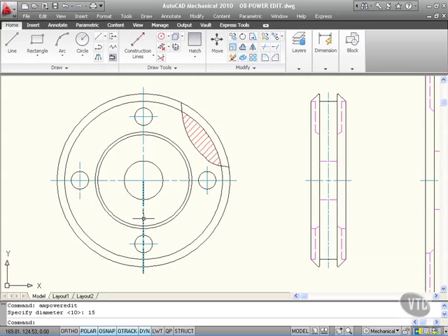If I hover over this center line here and double click, specify a diameter there, can you see I move, and as I come out I can do it freehand. Notice you can see the distance there in the box. That's showing at the moment as 63.17. If I change that to 65, let's say, and press enter, can you see there, look, the center line has now gone inside. It's smaller. So I'll just do a Control Z or an undo to take that back to where it was. So I can edit my AutoCAD Mechanical objects by just double clicking on them.